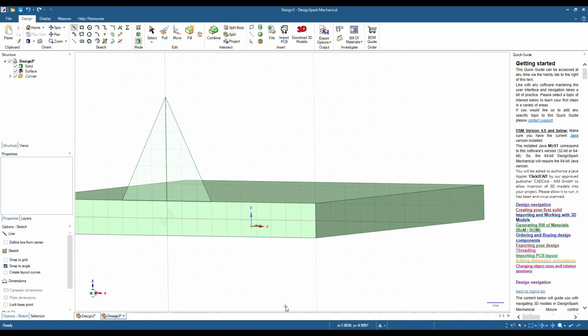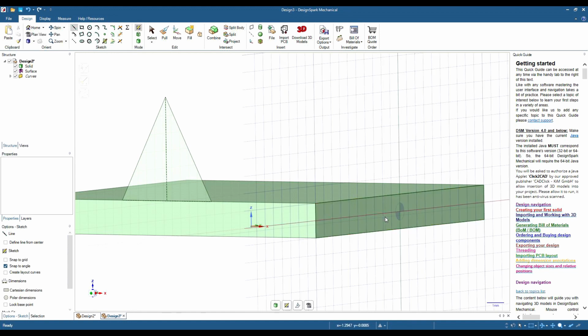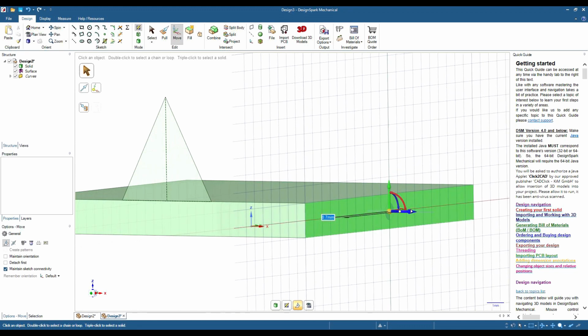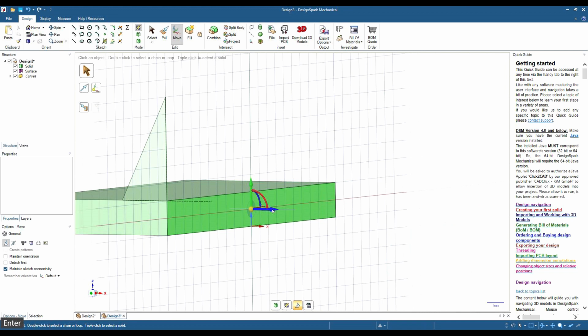This time we'll take it from this end here, but we need to be able to draw it from this point here down to the other side. We know this is 20mm, so if we move this sketch plane 10mm towards the center, we know that we're right on the center of our base object.